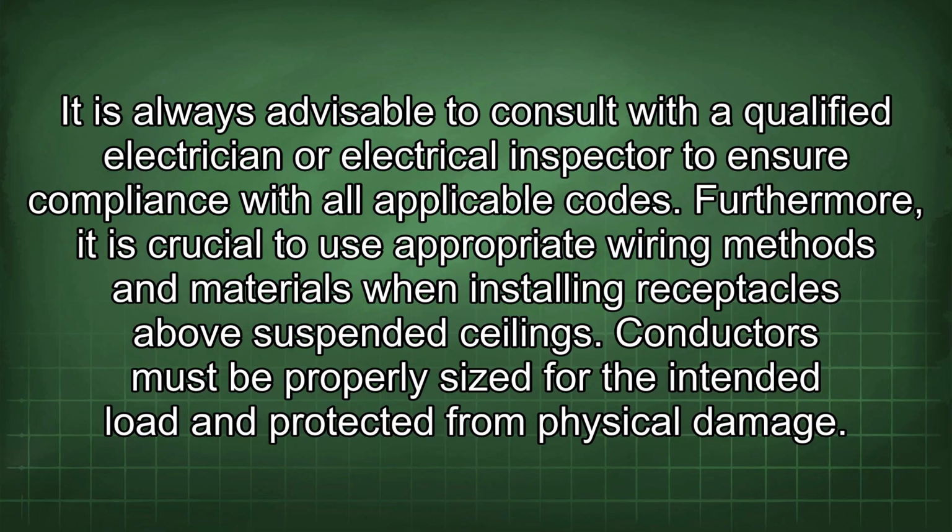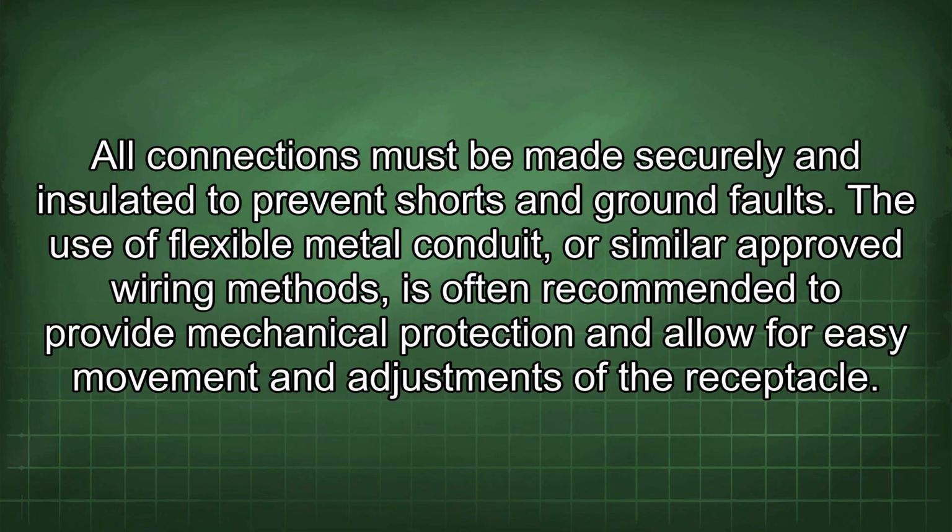Conductors must be properly sized for the intended load and protected from physical damage. All connections must be made securely and insulated to prevent shorts and ground faults. The use of flexible metal conduit or similar approved wiring methods is often recommended to provide mechanical protection and allow for easy movement and adjustments of the receptacle.